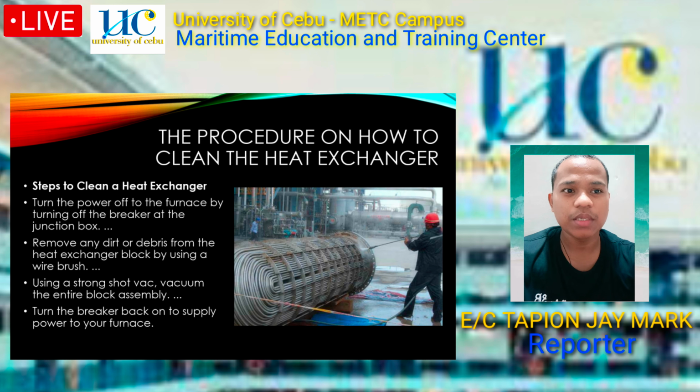But first, we have the steps to clean a heat exchanger. First, turn the power off to the furnace by turning off the breaker at the junction box. The second is to remove any dirt or debris from the heat exchanger block by using a wire brush.